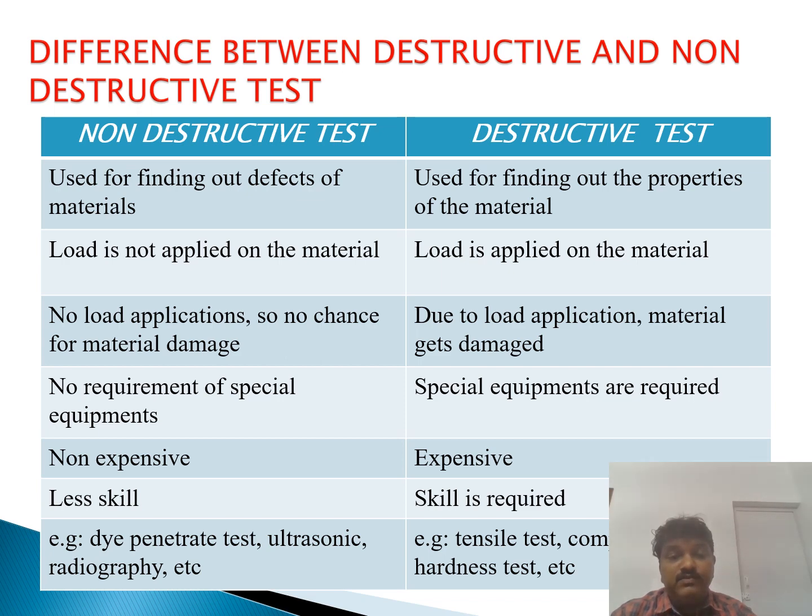No requirement of special equipment in non-destructive testing. Special equipment is required in destructive testing. Some of the examples of non-destructive testing are dye penetrant or liquid penetrant testing, ultrasonic testing, or radiographic testing. Examples of destructive testing: tensile test, compressive test, torsion test, etc.